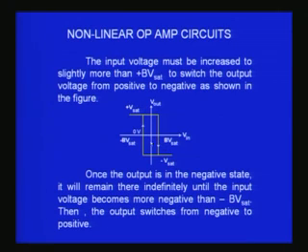Similarly we get a device hysteresis behavior, therefore it is called a hysteresis, and the difference in voltage is what actually matters for us with reference to a comparator, and this is made like this so that it can be unconcerned about the voltages corresponding to the noise.